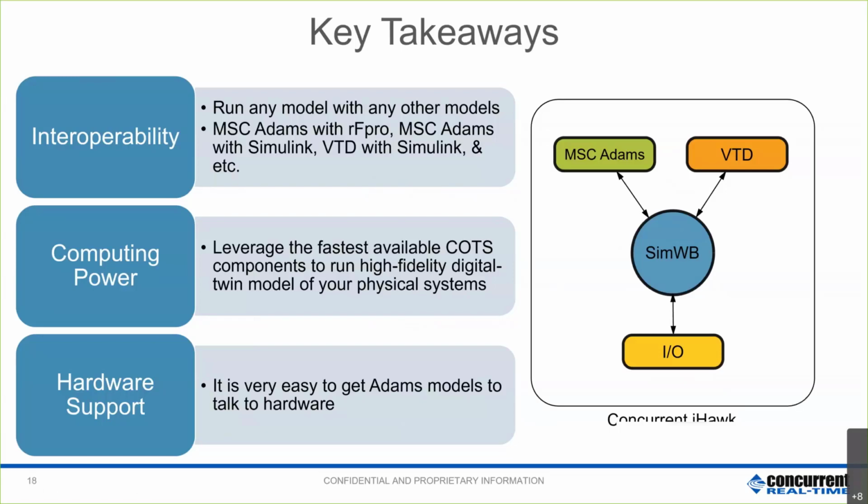And the third point is hardware support. Again, like I said, it's very easy to get the Adams model to talk to hardware without actually writing a driver, without actually knowing anything about the hardware. Everything is GUI based. All you do is click a button and you get the Adams model to talk to the I/O. So this comes back to one of the questions earlier: how do you get the people that are very well versed with simulation interested in HIL, SIL, and MIL? This is how you do it. You make it all very easy, GUI based.